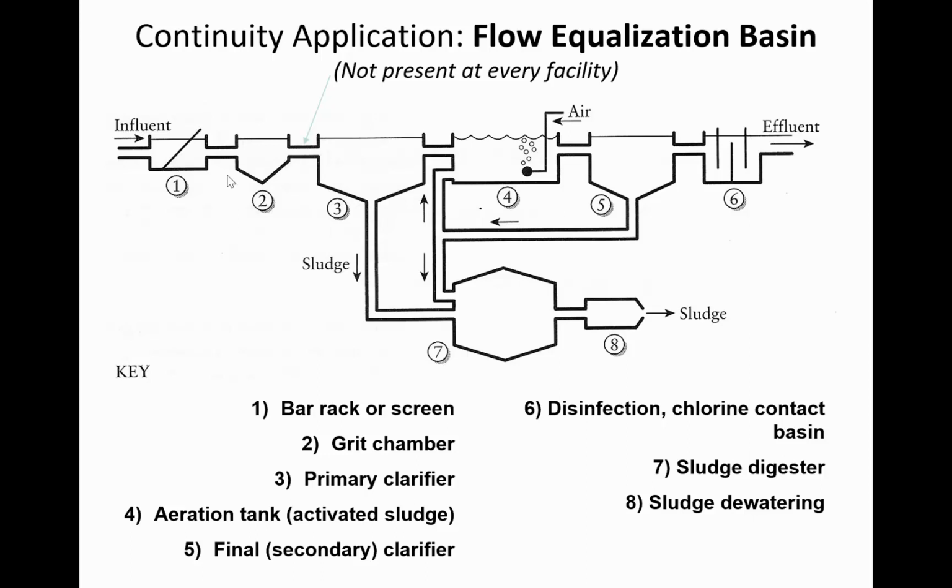And so that sludge that sinks to the bottom is sent into a digester, a sludge digester. The oil is scraped off the top and is treated separately, but then the rest of the water goes into an aeration basin. After the settling, there's still plenty of contamination in the water, but it's generally dissolved contamination. It may not seem like it, but even just sugar put into water, if it was discharged into a stream, would be a pollutant.